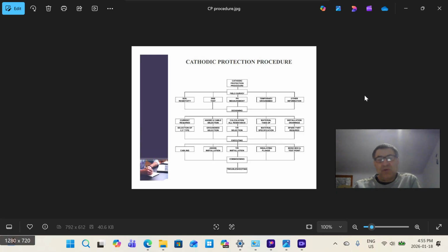We are not going to escalate the corrosion between the connected cable, which is copper, and the carbon steel pipeline. That's why we need to design the welding, and we need to have a specific welding procedure specification to connect the cable to the carbon steel pipeline.